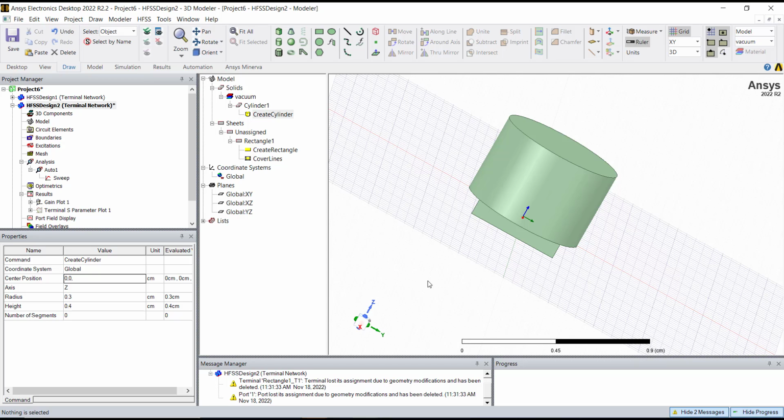And my Z position is going to be offset from the origin. If you remember, it's going to be offset half of the gap port height. If I go the full gap port height, it's going to be too high, just like when we originally mis-centered that gap port. So what I'm going to say is height, HEIGHT, and I'm going to divide it by 2.